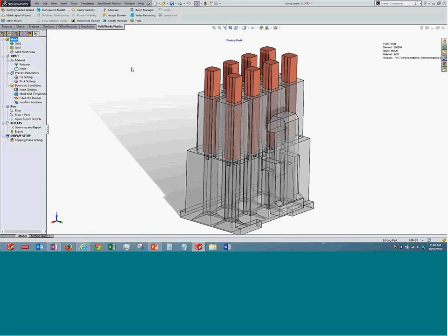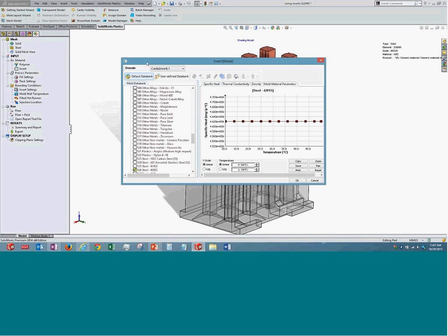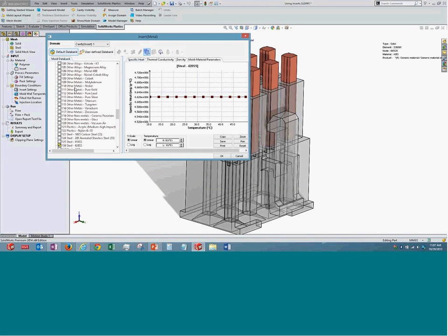Okay. Applying what you saw over here, the upper material input remains the same, nothing different. Now, this is a new thing that comes up over here: specify the material of the metal insert. This particular insert can be of metal or different things. So we have another database which is going to help you select the material for this metallic or solid component. It's being shown over here. Select any material and apply. So the necessary material details of the metal, like heat, thermal conductivity, density, mold temperatures, all those things.